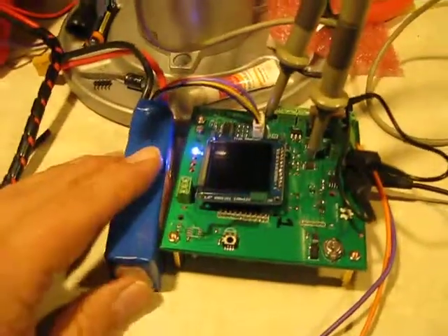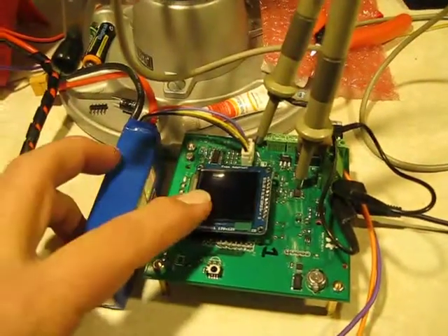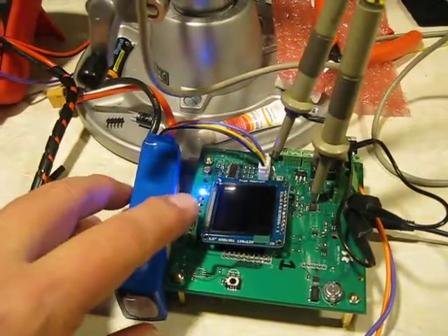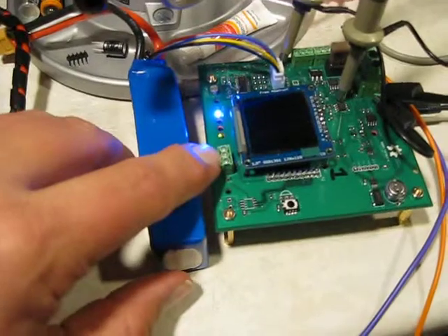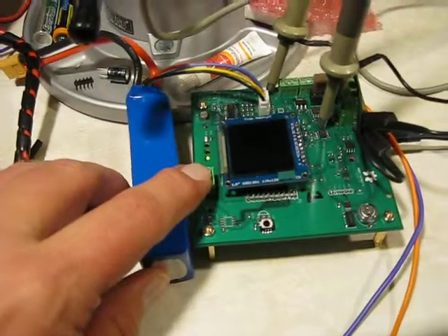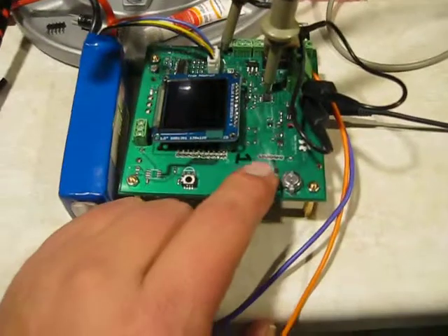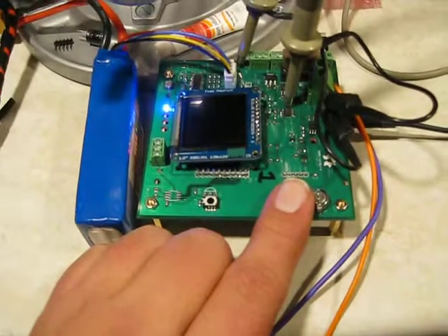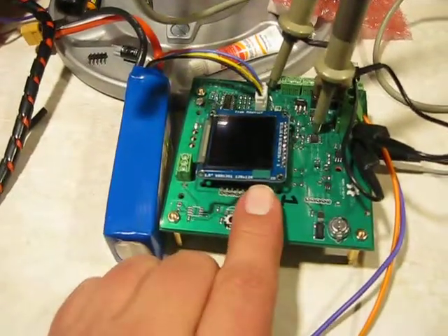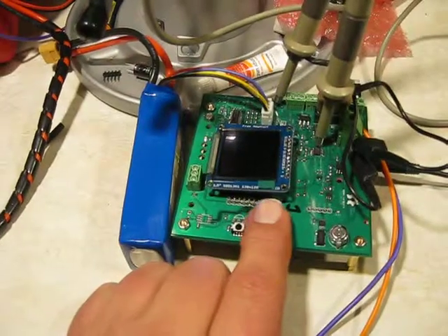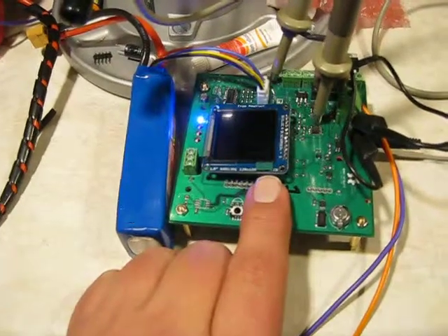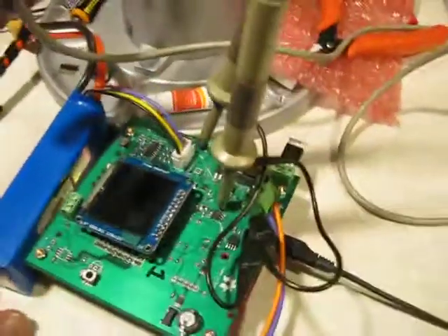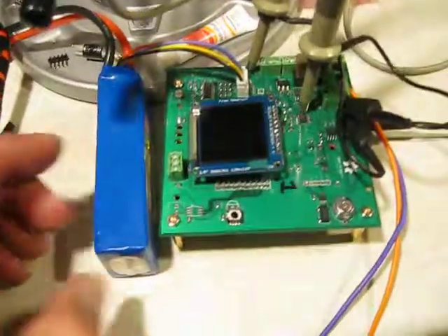So this thing's running like a champ. I have a lot more software to develop for the display, the IR interface. This is the one-wire interface to bring in all the temperature probes from the Dallas 18B20. I do have code. This is the real-time clock circuitry over here. I have code for the RTC to work right, so it'll be a data logger. This display also has an SD card right here. I'll have to implement SD FAT in the microprocessor. But this thing is running pretty well for today.